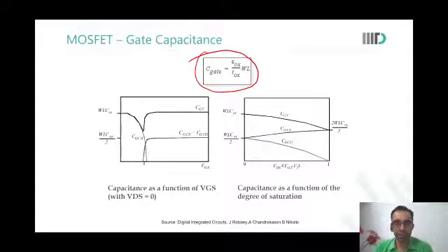Sir, a small question. While you were mentioning the pins on the drain and the gate, you said there might be more than one contact. So why are we taking more than one contact? Again, you make a P cell and make a device of width 2 microns. See how many contacts it will give you. Actually, I've made that, but it has given many contacts, sir. That was my doubt.